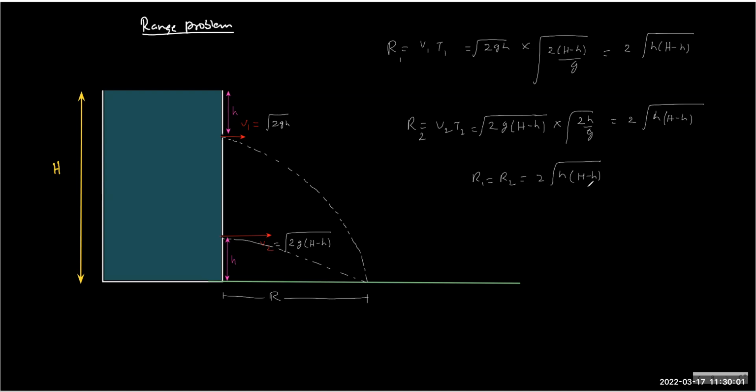And because it's a kind of quadratic equation, if you see inside the root, it will have some maxima and minima. So where must we punch the hole to maximize the range? That's common sense. You can say common sense. It must be the center, right? So the center will have the maximum range. So now, if your intention is to maximize the range, you know where to make the hole in the tank.